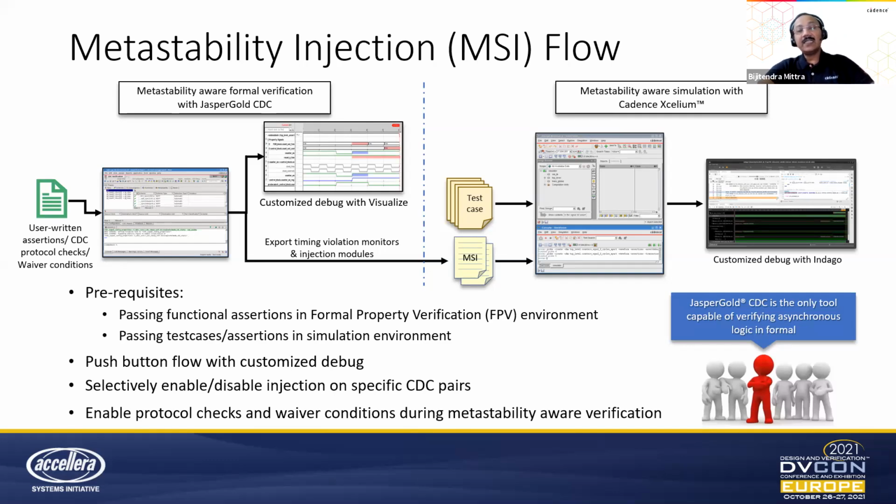Similarly, in simulation, you can pass on this information in the form of timing violation monitors and injection modules to simulation. All you need to do is include these metastability files into your simulation run file, and when you run simulation, your simulation becomes metastability aware.